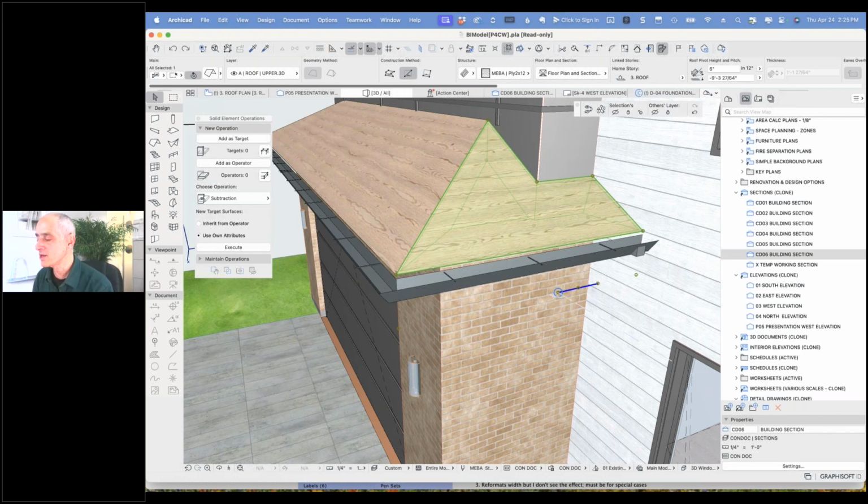When you draw a roof manually, you're going to click on 2 points in space or on the plan to say, oh, the plate line is parallel to this line in space. And then you either magic wand or trace or draft an outline for that polygon shape that we've got. Or you create something and then you cut it afterward. But this shape here could be any length as far as the roof itself is concerned. In other words, it could be short, it could be long. It's often right up at the edge of the roof or right underneath the supporting part of the roof, the plate line.